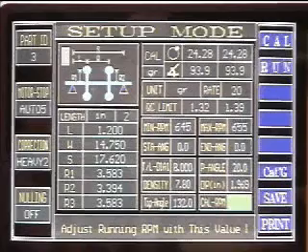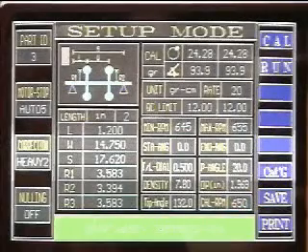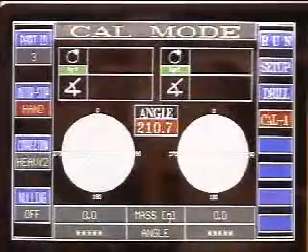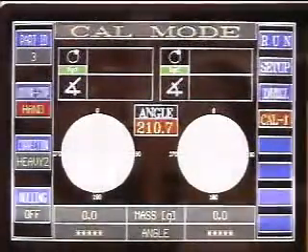Calibration RPM displays the speed setting of the previous calibration. Lastly is part name. Here alphanumeric, numeric, or a combination of both types of data for the part description can be input. Pressing the F2 key switches from setup mode to calibration mode.